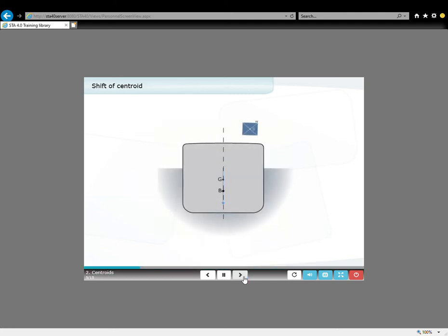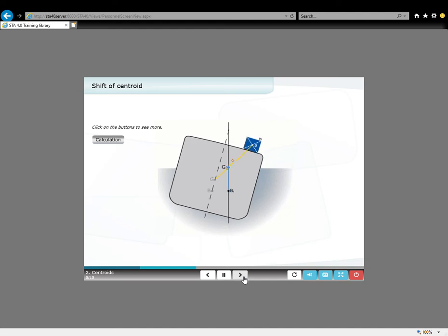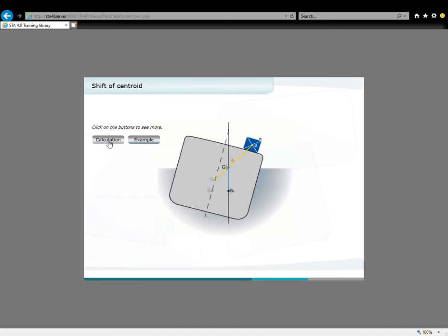When a weight is shifted on board, loaded onto, or discharged from a ship, the original center of gravity of the ship will move parallel to a shifted weight, directly towards the loaded weight, directly away from the discharged weight. On a ship working cargo, this will normally result in the center of gravity G moving at an angle from the center line. To make this easier to calculate, the movement is normally broken down into two parts, the horizontal movement and the vertical movement.